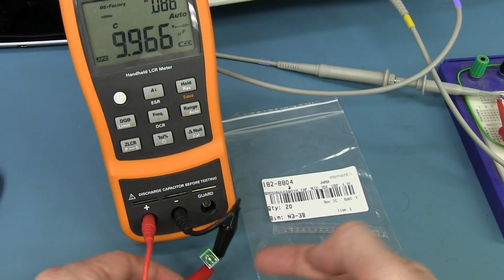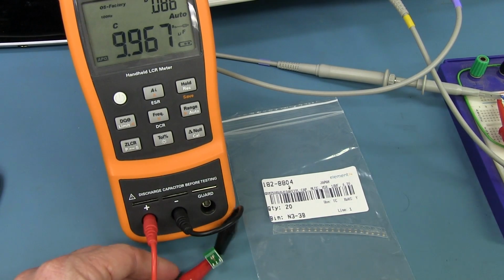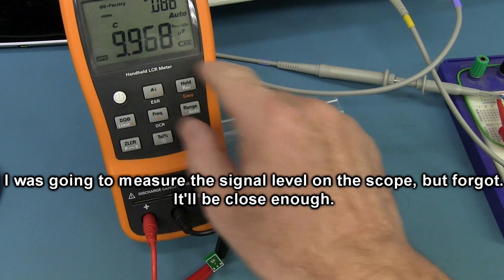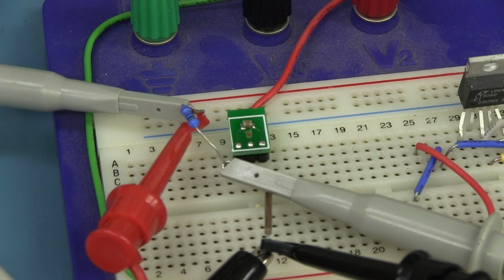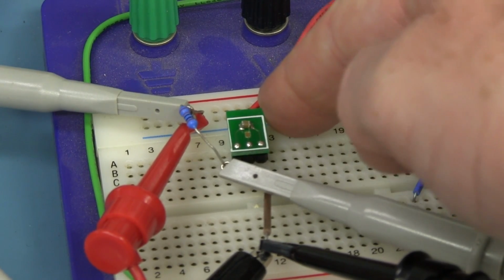Here it is. I've surface mount soldered one of the capacitors onto this little adapter board so we can plug it into our breadboard. Now, it's completely cooled down from the temperature change. It's at room temperature. We're like 23 degrees C here in the lab, so the temperature is not going to change during this measurement. And 100 hertz, here we go. Look, we're practically bang on to our 10 microfarads value. Okay, let's round that to 10 microfarads. This is spot on. Okay, so let's mount that on our breadboard here. We've got our bang on 10 microfarad capacitor there.